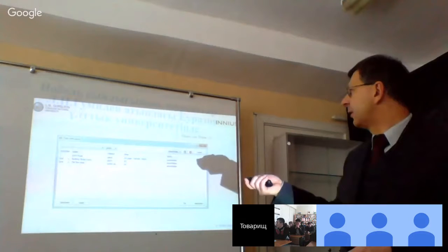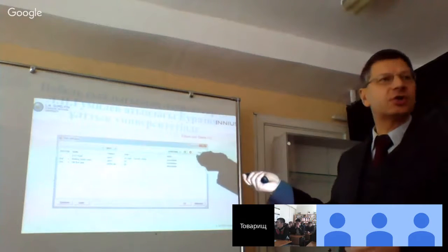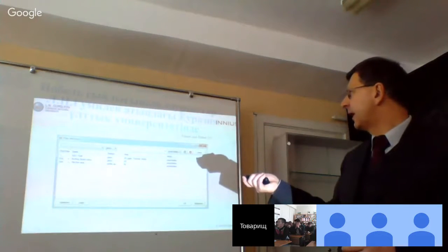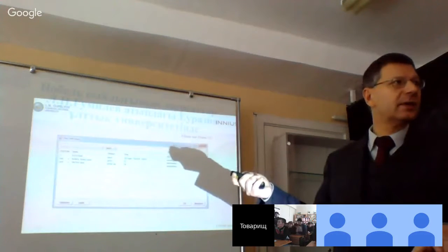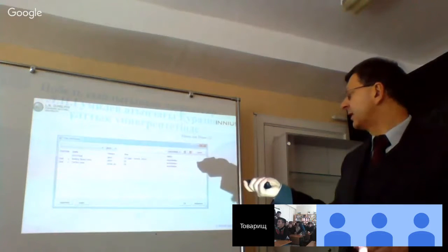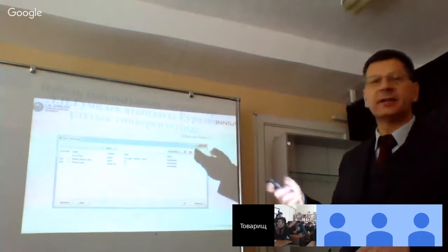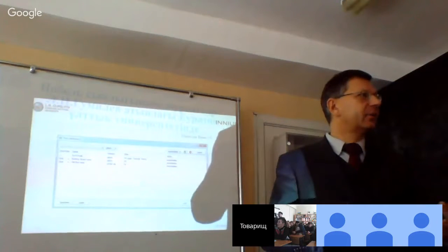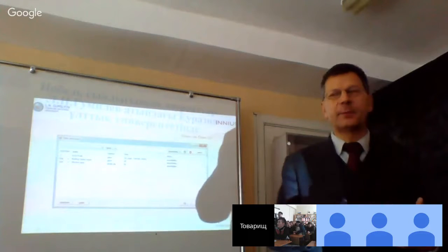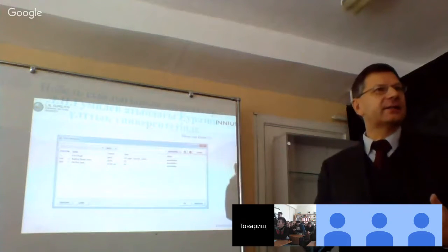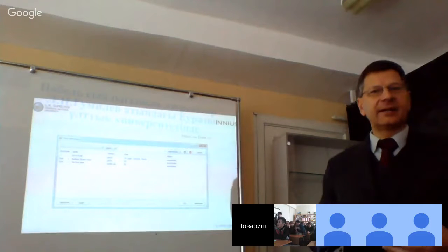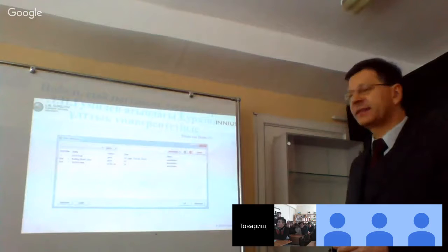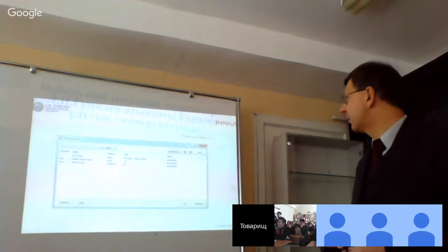In this case, I want to find the storage rooms on level 0, and I want to find the storage rooms that are larger than 50 square meters. And as you see, you can combine a lot of information to get the result for your building. And so you can speed up your process because you get the information faster.